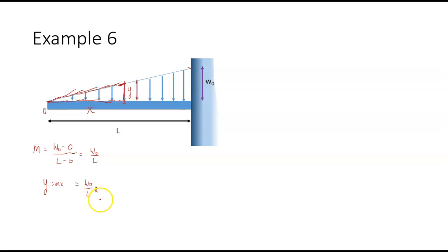And we can say then that is the value. If I want to get the force then, I need to work out what the area here is. What's that area? It's the same over any triangle, so the shear force V will be, for any triangle, y x over 2.